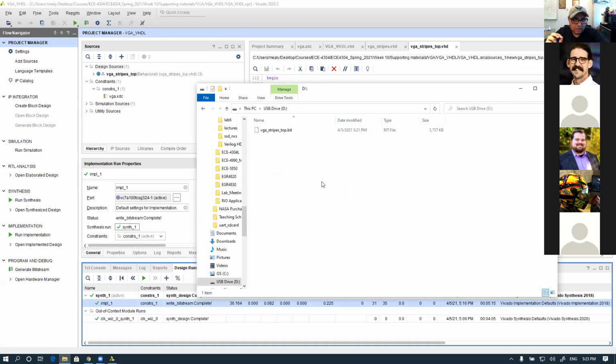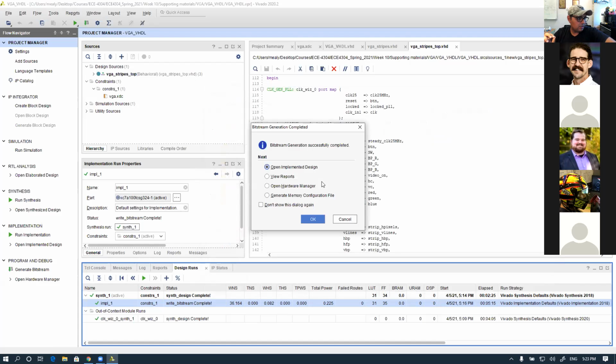The SD card. So I'm going to unplug the SD card, take it here, and put it where? In our SD card slot here. So you just put it there. Are we done? No. So we need to find the jumper saying SD.